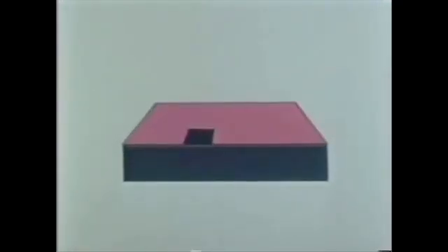To protect it from the outside world, we allow oxygen to react with the top surface and grow an oxide called the passivating silicon dioxide layer. Now we're going to make use of the masks we made earlier. First, the wafer is coated with a photosensitive resin. The mask is then placed on the wafer, and the system is then exposed to light. As a result, the exposed resin hardens. The remaining resin can be simply rinsed away.